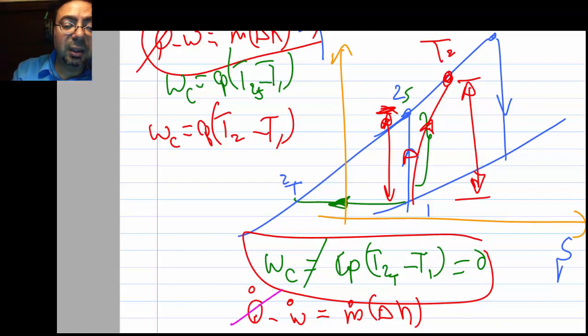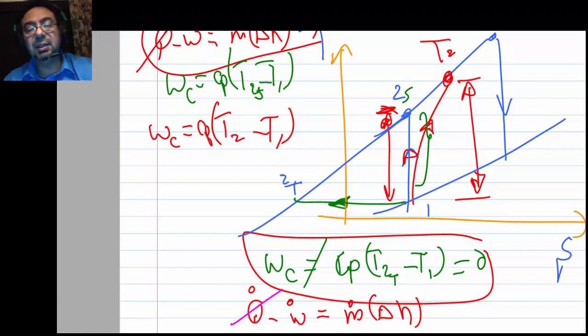It's this guy. I cancel it before because adiabatic or isentropic. Here is isentropic and here is adiabatic. Both of them have Q dot 0. But if I go isothermal, will Q dot be 0? No, it will not. How do I actually go isothermal? How do I compress the gas in isothermal fashion? I will have to always remove the heat. It wants to get hot as you compress it.